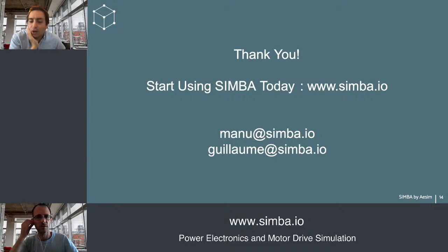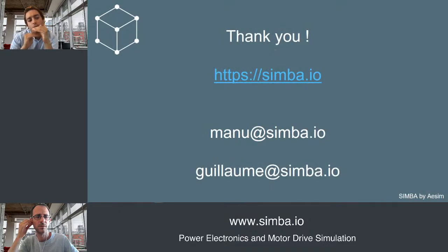Actually, I can answer. So basically, the way it works for now is for digital control, we use the C code block, and we have a default template for Z domain transfer function, and we use an external clock. So you can specify basically the sample rate that you want, and the Z domain transfer function will be evaluated at a given sample rate. And this is completely independent. This will work fine even if you use a variable time step solver.